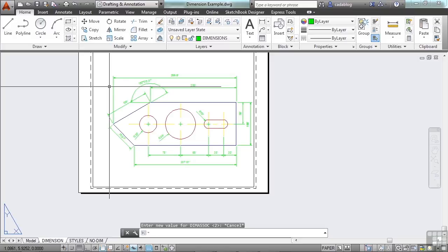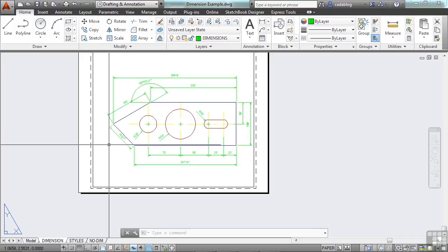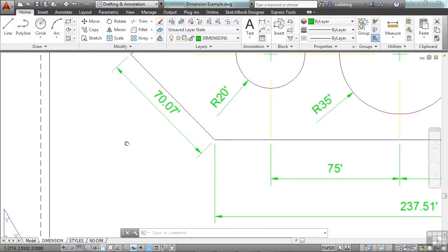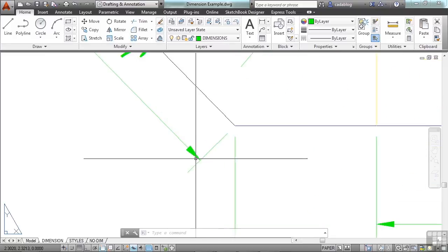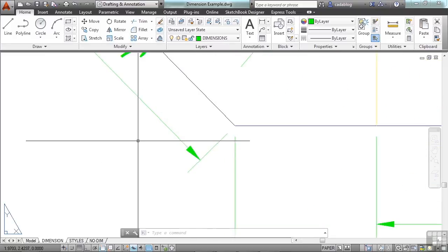That means that it's just a collection of separate objects, like a line or text, a block for the arrowhead, etc. It's not a dimension object. Therefore, if you want to edit that dimension, you have to delete each individual piece and recreate it, or move each piece as if it were line work. Dimensions have several distinct elements to them. They have their text, dimension lines, arrowheads, and extension lines. All of these can be controlled, defined, and altered through the dimension styles or through the properties manager.